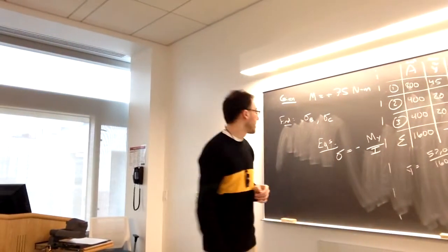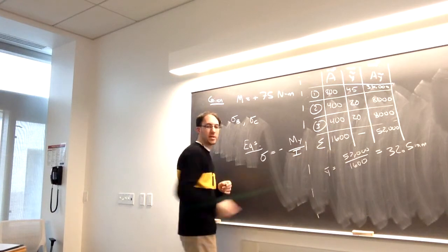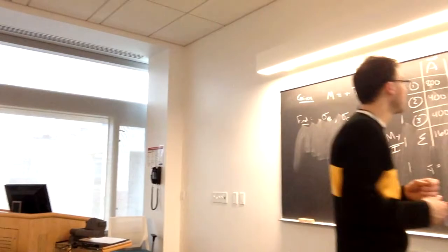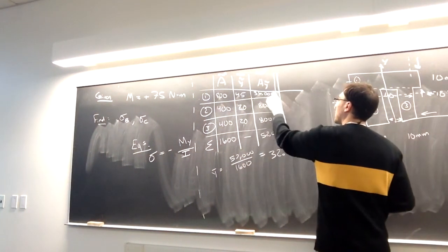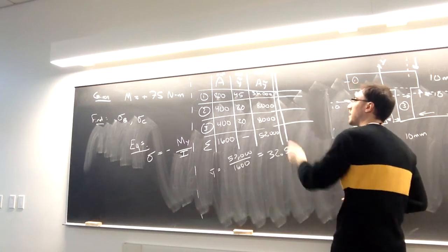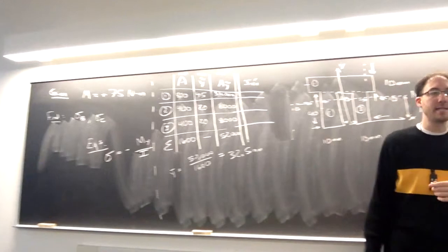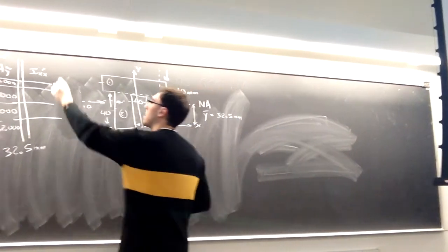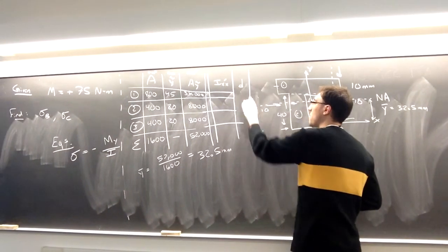Okay, so I need that to find the y over here. But I also need that to do the next step, finding the value of I, the value of that moment of inertia. I expand my table. I want to know now for each shape, what is its area moment of inertia about its own centroid. And then we have to use the parallel axis theorem as well.